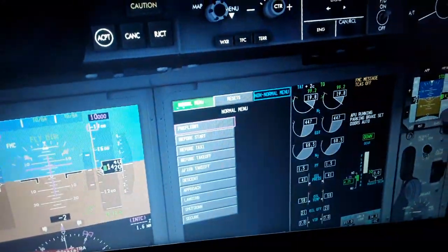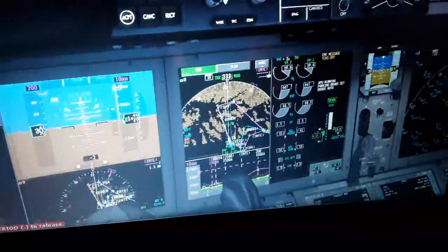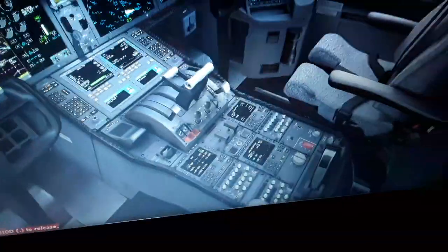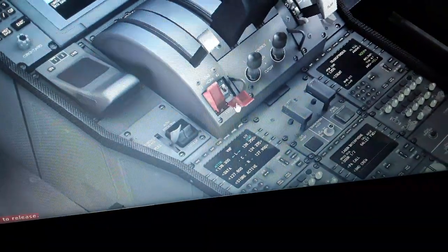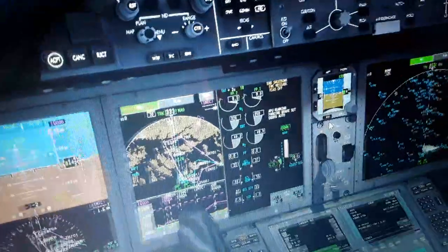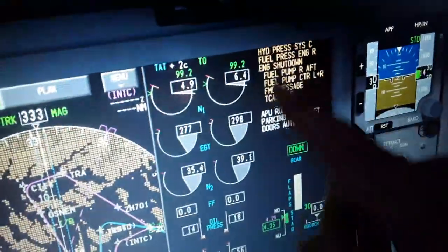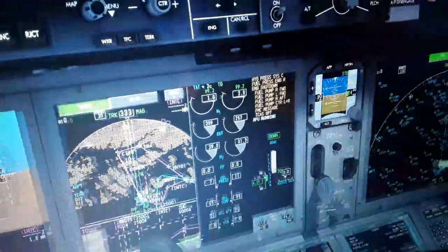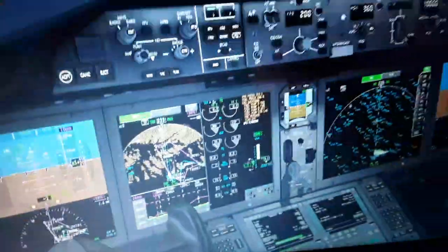Also communication. So we go back to the navigation display. We'll see now, we turn off the engines, both of them. Fuel control in the off, fuel valve in the off position. So you'll see the message, we have the fuel booster pumps off, and the engines are decreased.